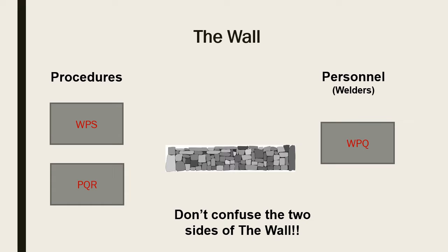Imagine how much trouble it would be to try and produce welders that were qualified to hundreds of different WPSs. Company I worked for, we had dozens and dozens of welding procedures for 7018 alone. And they were all written for different customers, and there was all kinds of craziness on it. But our welders, you give them one test, and they're covered for all that stuff, because there's only 5 or 6 essential variables in a welder when you qualify a welder.